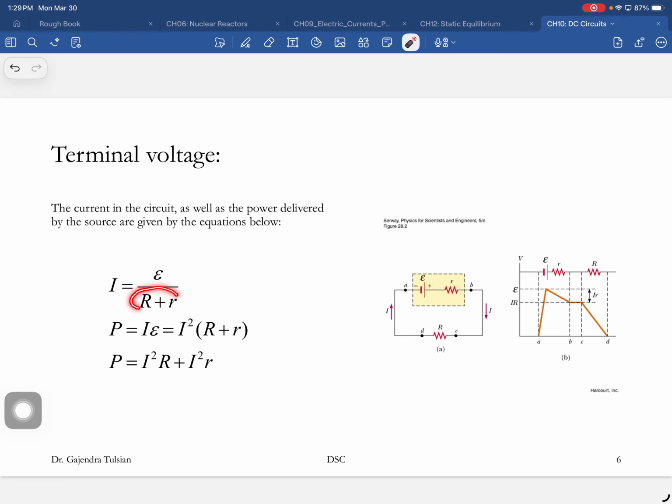Here are resistors in parallel. So you connect it like this. Now, each resistor sees the same voltage. So when you connect devices in parallel, if you connect just this one to the battery, it will get a certain current. And if you connect something else in parallel, the amount of current here does not decrease.